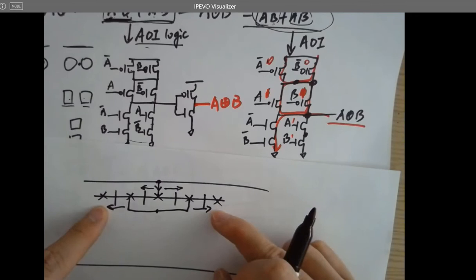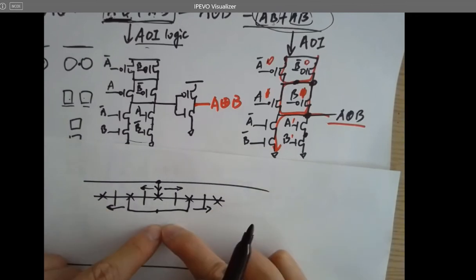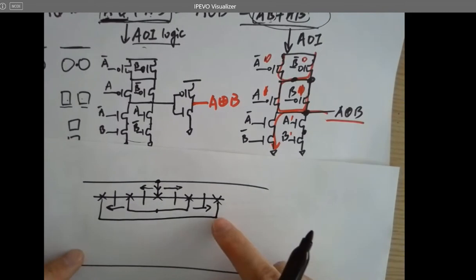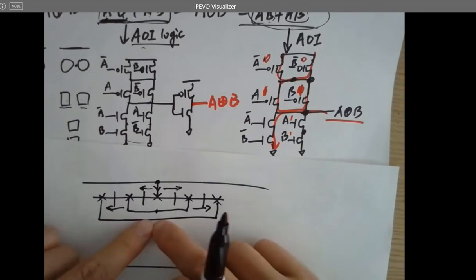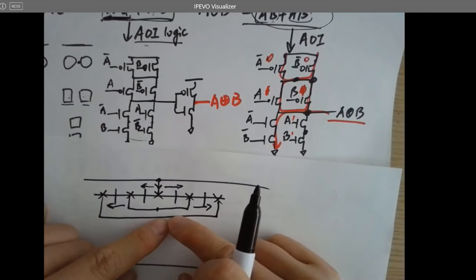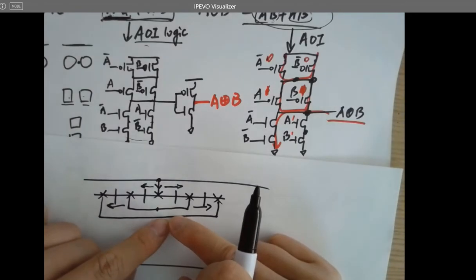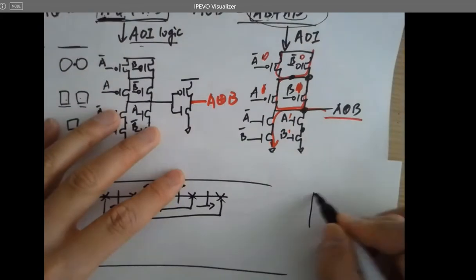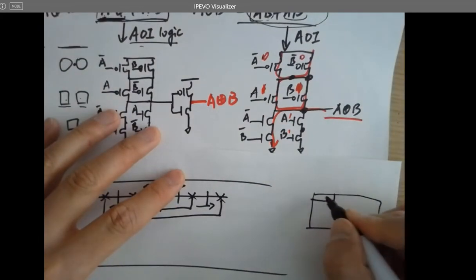Split, split, merge. What's this material? What is this wire? What's the material here? What's being shorted to P plus to make the connections for the P plus and N plus, for the drains and sources? What's the material to make all the connections? Metal 1. Because the substrate is at the bottom, at P plus.